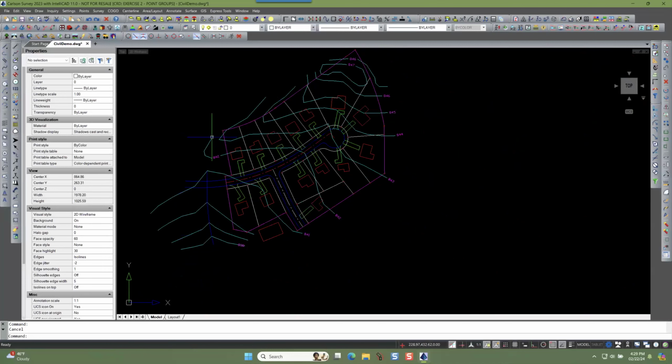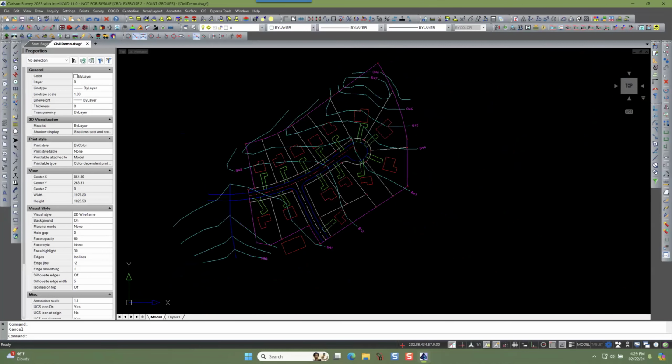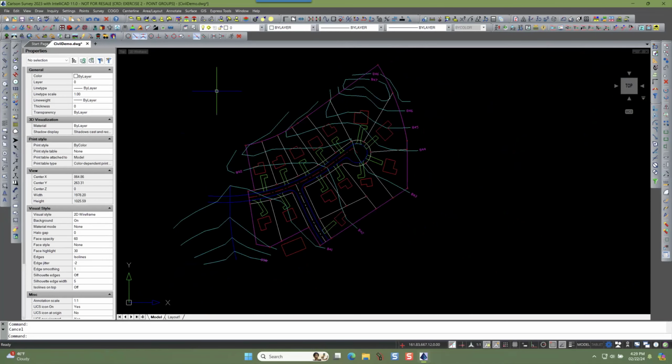I don't think it's in the OEM version that you have, but Carlson gives that to you. That's why Carlson wrote that command, because it might not be in these older versions of AutoCAD. And then you've got some other things up here, where I do this freeze by pick and freeze. You've also got turn off by pick and turn off by selection. So that's the difference between freeze and thaw and on and off.